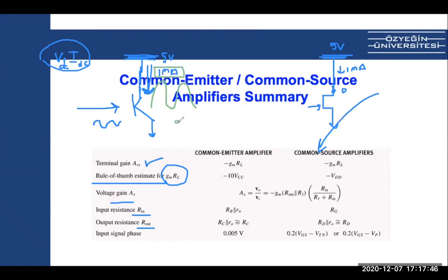And that is actually called the transconductance, right? As I described several times. It defines your current divided by your voltage in the AC domain. So how much current swing you are getting at the output. If you remember the small signal model, when we draw it, for instance for a MOS, there is this gm VGS here, right?